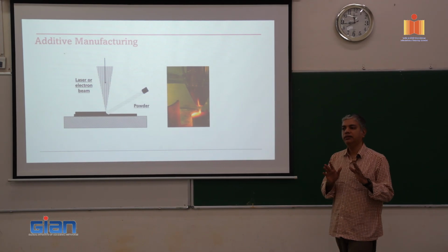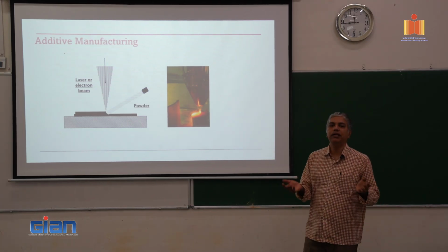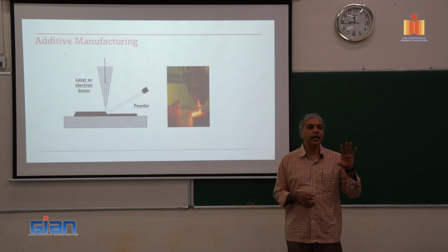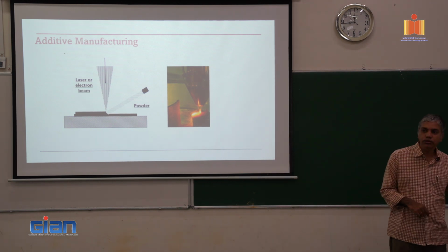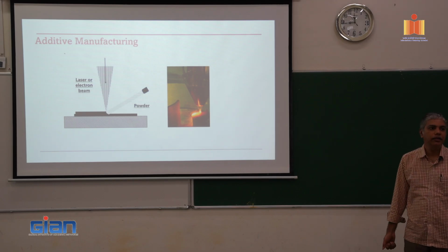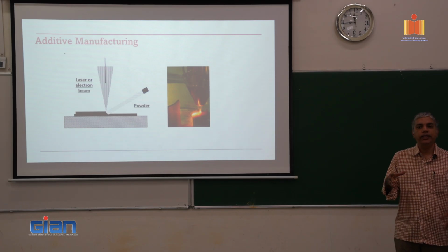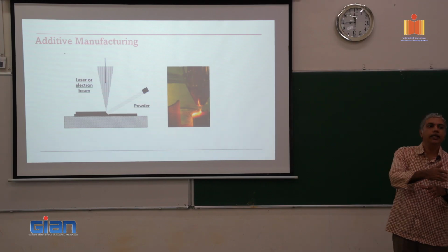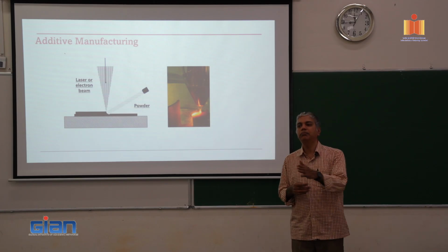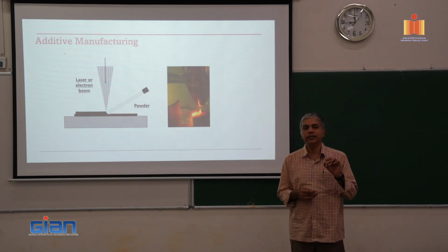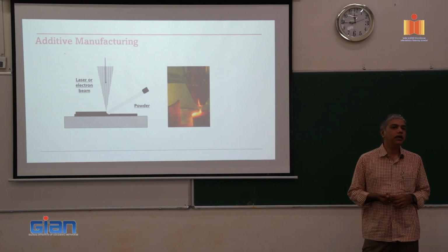Okay. So in additive manufacturing, there are multiple techniques, but the most common of them are powder bed and DED. But not all of them are suitable for repair applications. Why? Because if you take powder bed, for example, you are spreading a thin layer of metal powder, and then there is a blade. So repair applications in powder bed are very difficult.